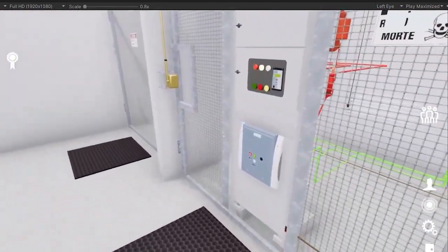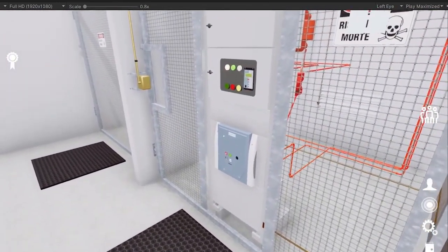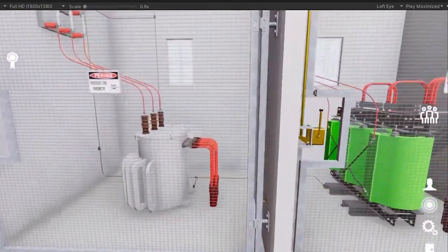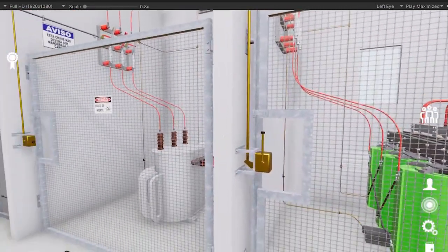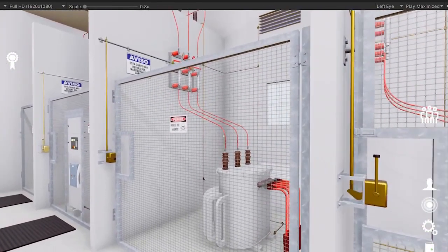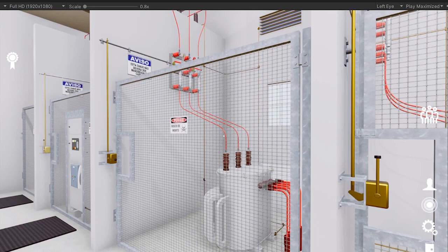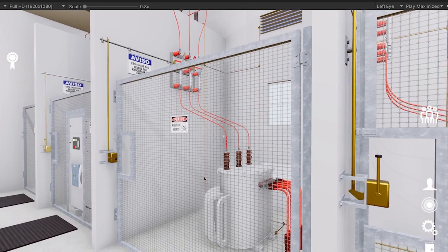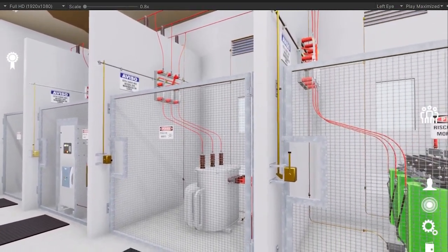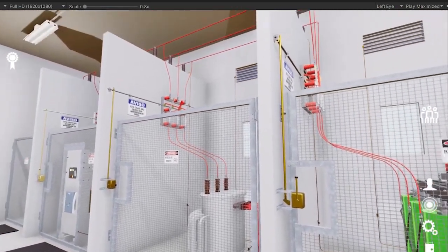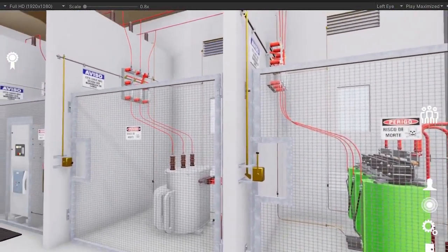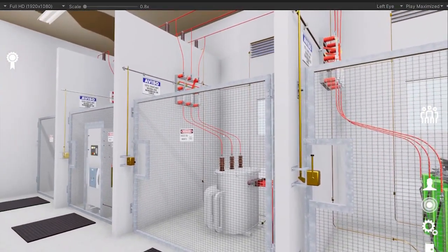I'm going to come here, close my circuit breaker, energized it, listen to the sound of the transformer, and it's energized. And why did it energize, folks? The bottom part of this transformer here is the return. It's the voltage return that comes from the panel. It doesn't mean it's connected to the grid, it's just the voltage return. So the voltage passes through this transformer, goes to the panel, and comes back through here, but that doesn't mean it's operating.